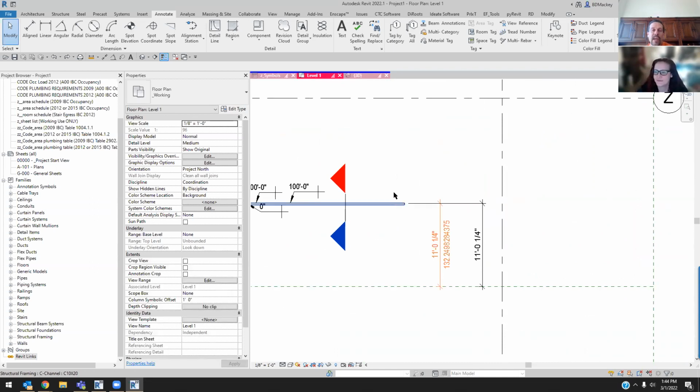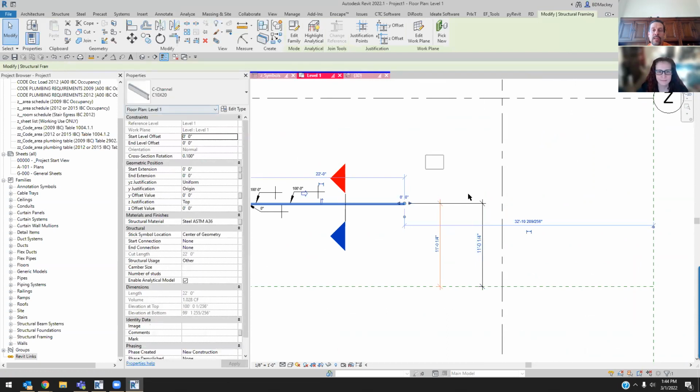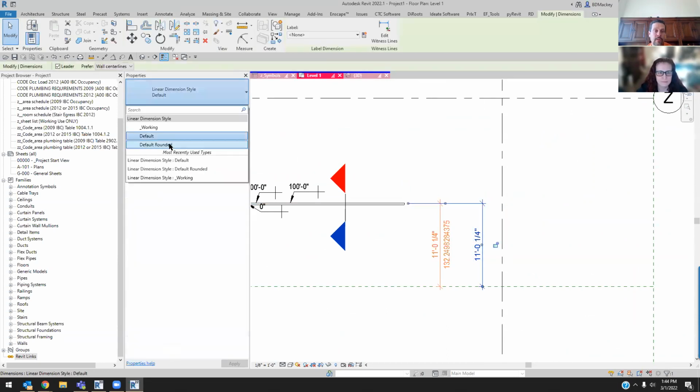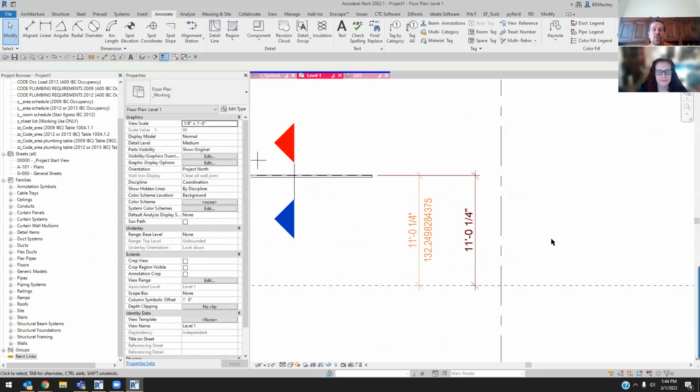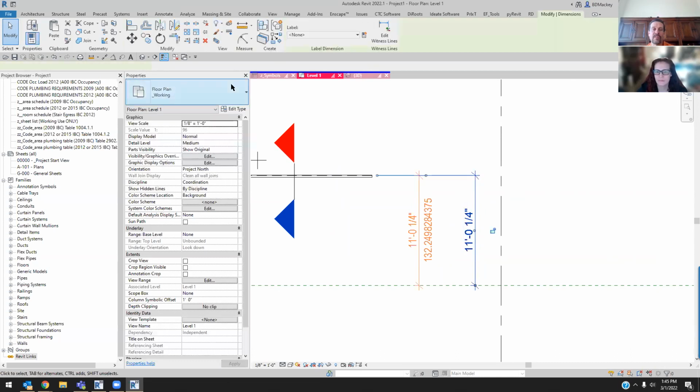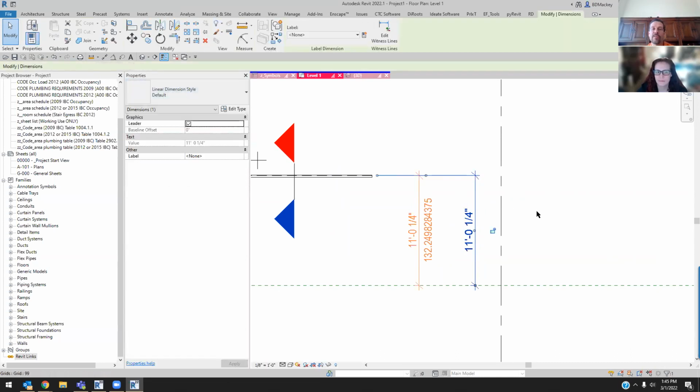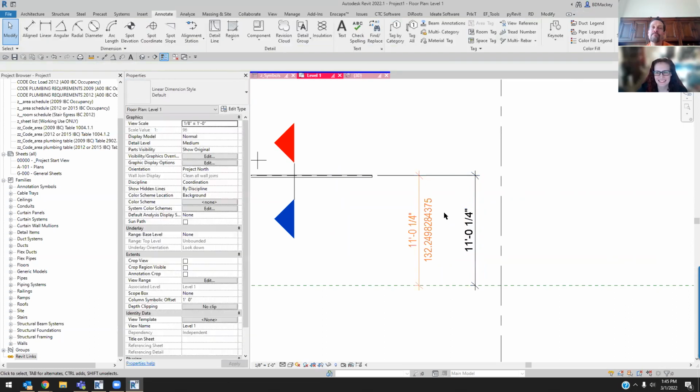And in the event it's an angled wall or there's some number where I need that to be, yes, I have a dimension string called rounded. My dimension string called rounded changes it to a very dark shade of red. So I know this has been a rounded dimension and there's probably a reason for it. And I have clients who follow the same procedure and weekly we go reset the dimension style back, the non-rounded one, the normal one. We go reset it back to 256 of an inch before people print and we watch all this stuff get bust on the prints. It's like, well, should have modeled it properly. Yes, I have clients who believe in my theory of be an asshole as a BIM manager. People will start following procedures.